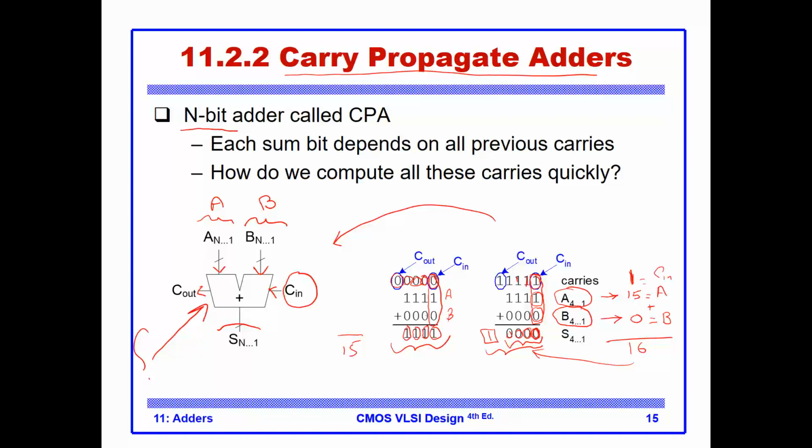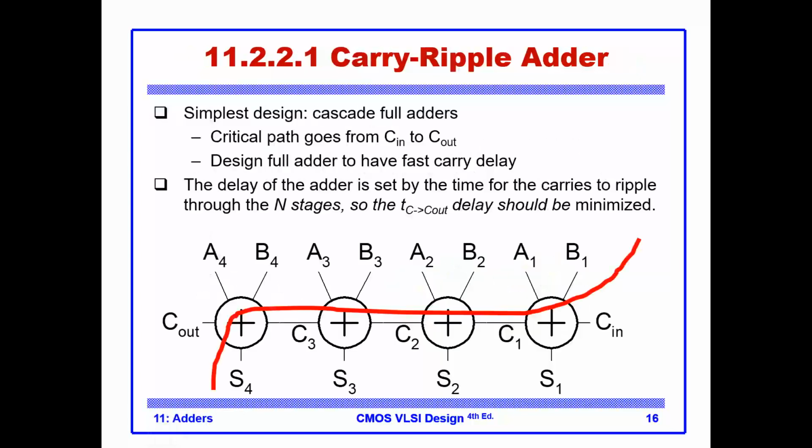Let's make an observation here. In these additions, when I was adding bit position by bit position, it seems that I was adding three numbers and generating a sum and a carry out. Well, I know that this can be done by what we studied in the previous lectures, by a full adder. The full adder has an input of 3 bits and an output of a sum and a carry. And therefore, this adder can be constructed by the following scheme.